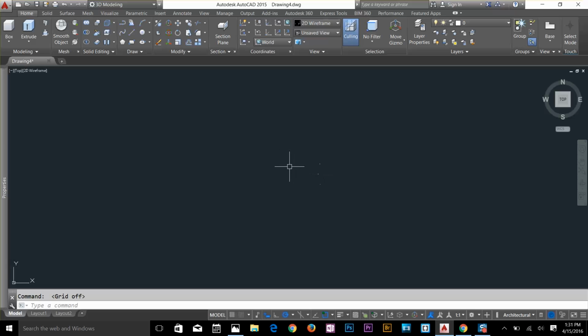So the area we have for our drawing would be, an X value would be 25 feet and Y value would be 60 feet. So, well, I'm not sure about the area, so I'm gonna start by drawing a line. So I start from this arbitrary point and I give a value of 60 feet. That's roughly 60 feet, and I start another line from here to 25 feet, and then I right click. You can use enter, right click or spacebar, whatever you like.